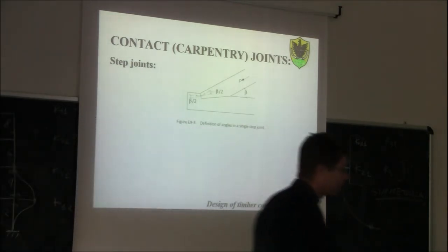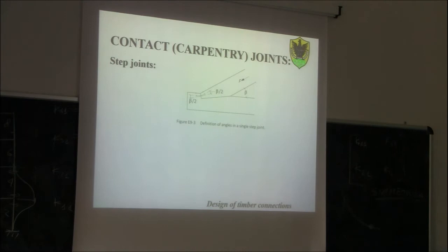Geometrically, of course, it will be a matter of decomposing our forces into different directions. And of course, when it comes to drawing a joint like this, there are some rules. For example, usually this notch here is cut by making sure that those two angles are the same.